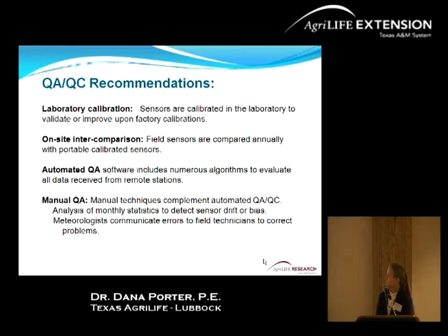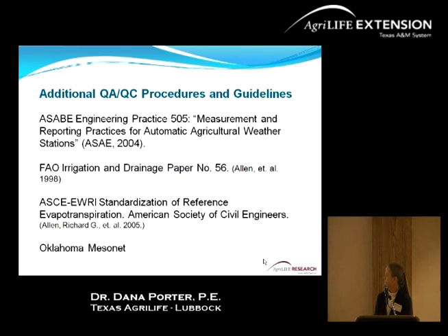Do an on-site intercomparison where you have side-by-side comparisons with the same type of sensor at the same location. Are they giving you the same answer? Automated quality control that is complemented with the manual control, looking at those data.